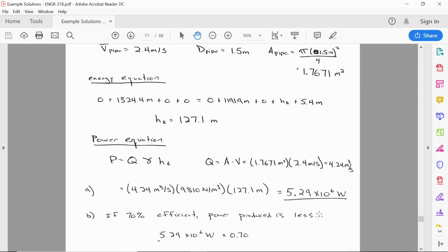So 5 megawatts. What happens if the flow rate goes down? If the flow rate decreases, then you can't generate as much electricity. That's one of the problems when there's a drought, like out in the west where they have these long stretches between rainfall. They have a lot of dams, and many of them are hydropower dams. When they have really dry conditions, they can't send as much water through the penstock because they're trying to conserve it. And when you decrease the flow rate, then you're decreasing the amount of power that can be generated.